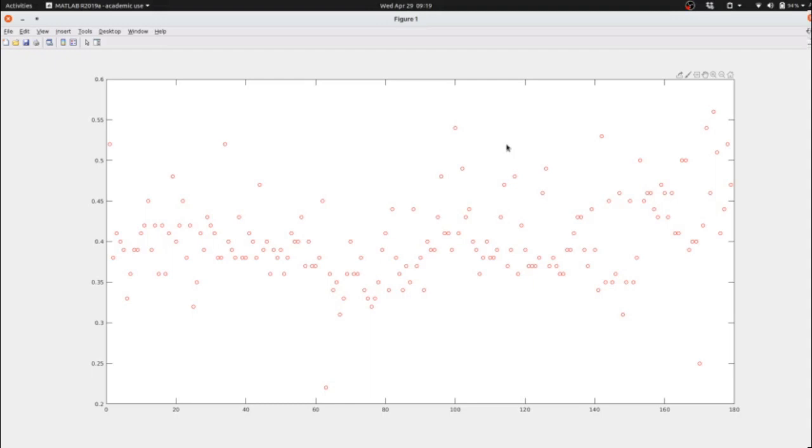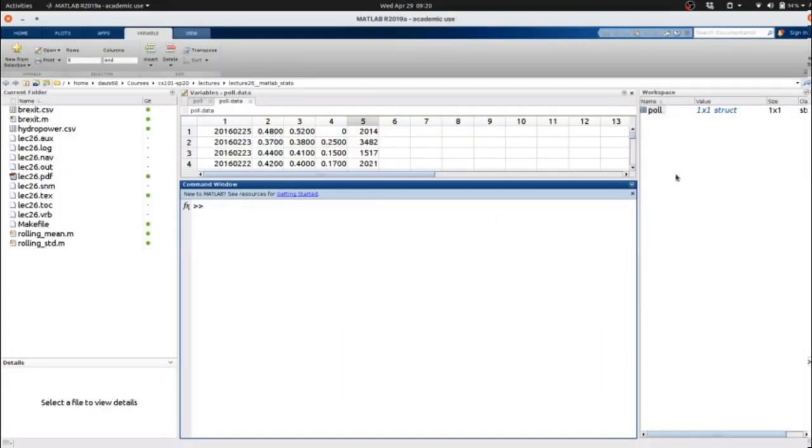So every time you run the plot command, MATLAB clears the data from the previous plot, unless we run a certain command called hold on. When we run hold on, this stabilizes the plot so that we can continue to add and manipulate the features of that particular plot. So let me go ahead and clear the console here.